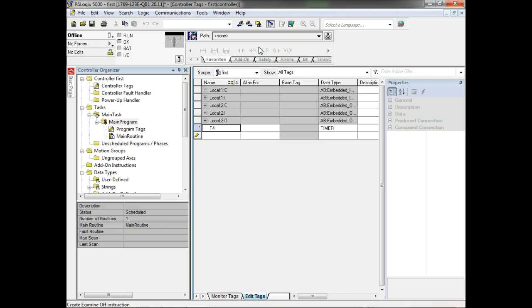So these are built into the PLC, but what do we have the ability to do on these hybrid PLCs? We can pop the side cover off and slap another module on. Then you have to come into your IO configuration down here somewhere and add those modules that are not built in. It isn't like the Siemens, where it picks it up and adds it itself. You have to add it yourself on here. Well, no, it picked it up and added it itself if you slap a module on.